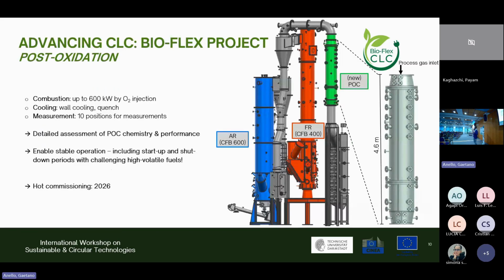And as I mentioned, the second big thing for our work here is this post-oxidation part, because it maybe sounds quite easy to just add some pure oxygen in the reactor outlet, but in the end, this will need a separate reactor. And this is something we now include in a more, let's say, sophisticated way, and also in a way much closer to how we imagine this post-oxidation could look in a commercial plant.